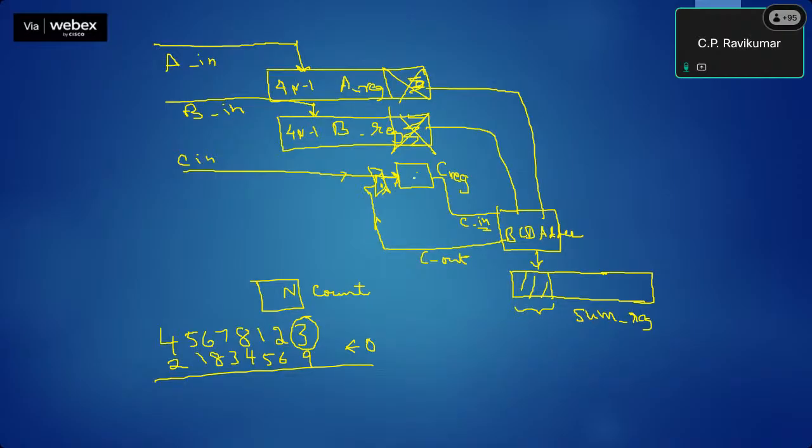So the 0 will be sitting here. So 0 plus 3 plus 9. Our BCD adder will provide 2 as the output. And there will be a carry out, which will get loaded into this. And everybody will shift. So this will go away. We'll get possibly zeros on the left-hand side. And the sum also, the 2 will get shifted and 2 will go here.